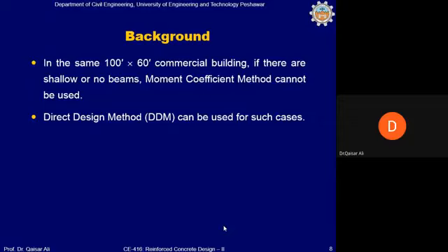Because if there are beams in the system, then the overall story height, which includes the headroom, must be kept such that it accommodates usual living conveniently. The minimum standard for a headroom is 9 to 10 feet clear, depending on the purpose of the building.